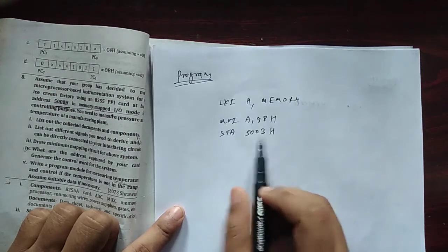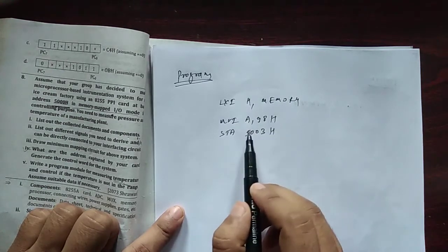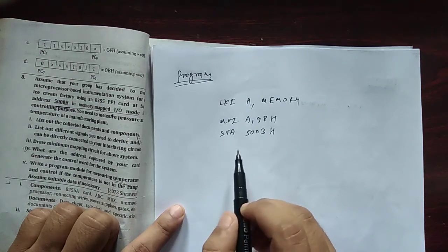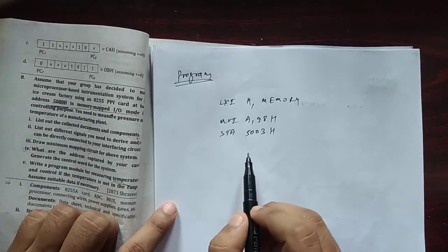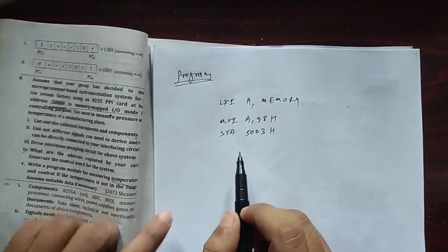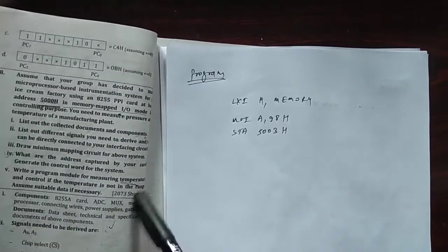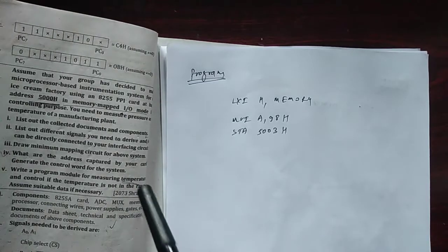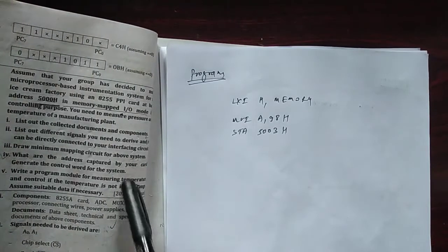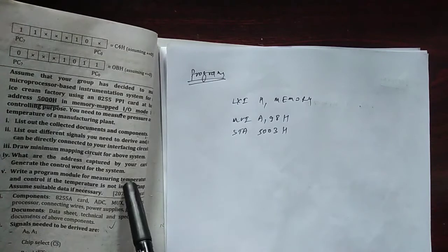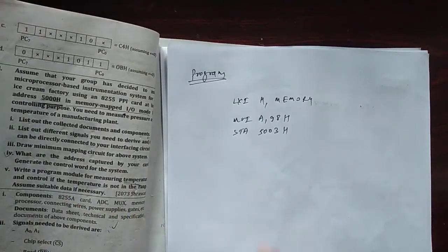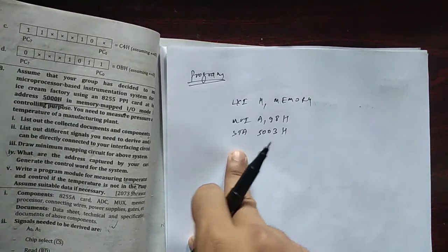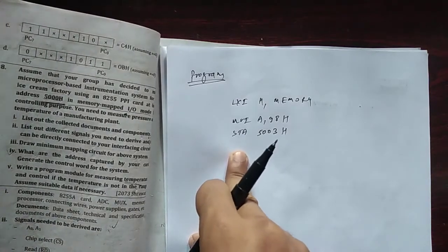After outputting the control word to the control register, we would normally set or enable SOC, but in this case we have two inputs, temperature and pressure, so we need to specify which input we will be processing.